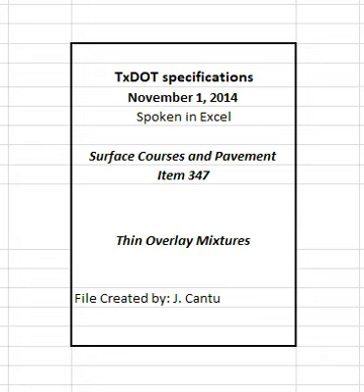The engineer may require the contractor to remove and replace, at the contractor's expense, areas of the pavement that contain irregularities and areas where the mixture does not bond to the existing pavement if the engineer determines that the irregularity will adversely affect pavement performance. The engineer may require the contractor to immediately suspend operations if irregularities are detected, or may allow the contractor to continue operations for no more than 1 day while the contractor is taking appropriate corrective action.